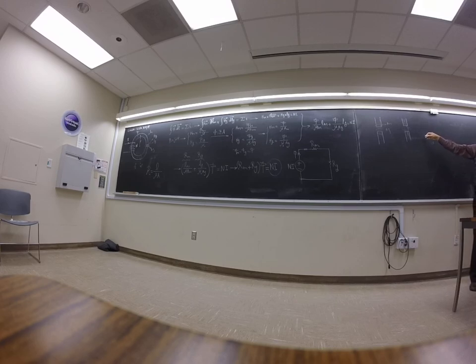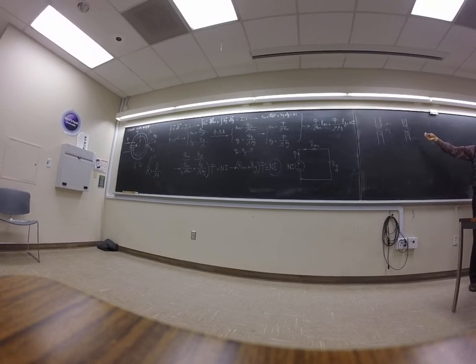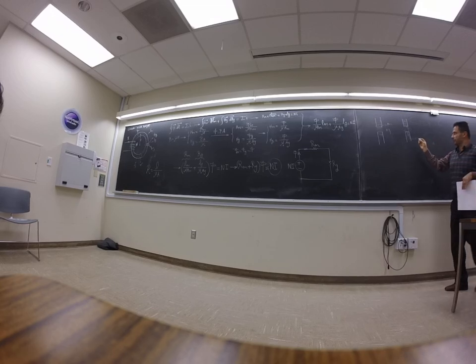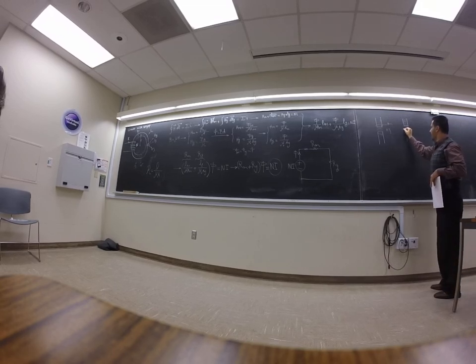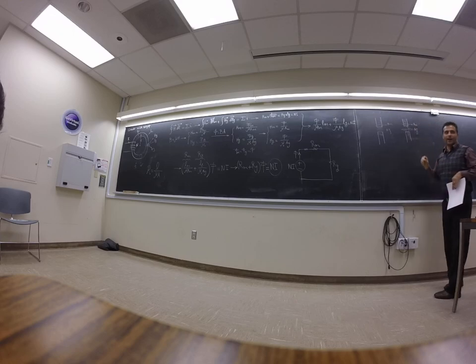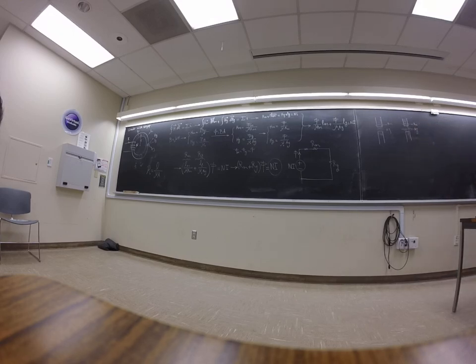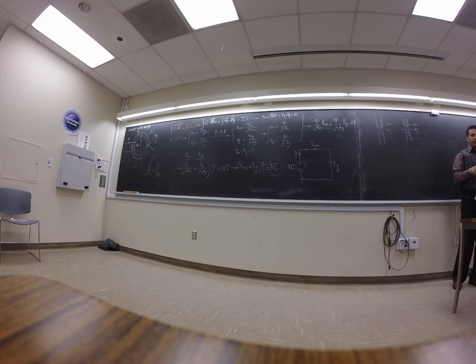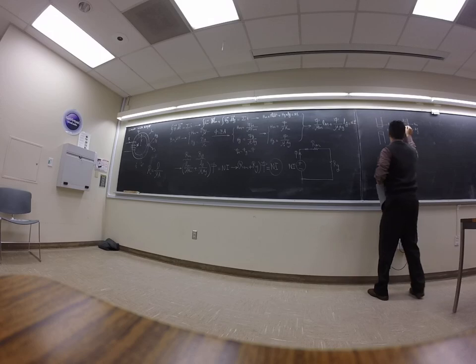If you do finite element, you can see, nowadays it's easy. If you even go type in Google, you say fringing flux in the air gap, it'll bring you some pictures of those, where you can see the finite element result if you are interested to see. See this one now is the Ag, right? This one is the Am, right? The flux is going to open. They call it fringing flux. Flux is going to open up. In reality, it's going to be like this. Usually they say, let's say, I'm going to give this one a little bit dimension here.